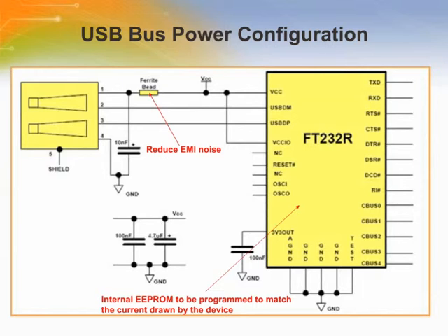A bus-powered high-power USB device should use one of the C-bus pins configured as PWREN and use it to keep the current below 100 milliamps on plug-in and 2.5 milliamps on USB suspend. A device that consumes more than 100 milliamps cannot be plugged into a USB-powered hub. No device can draw more than 500 milliamps from the USB bus.